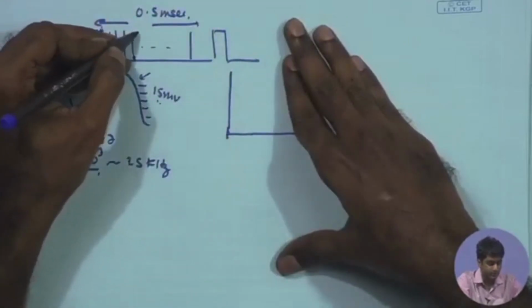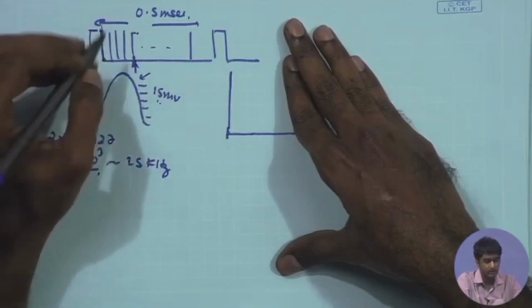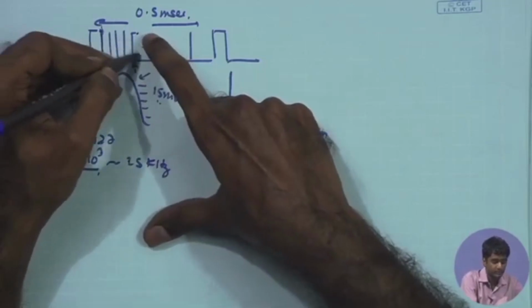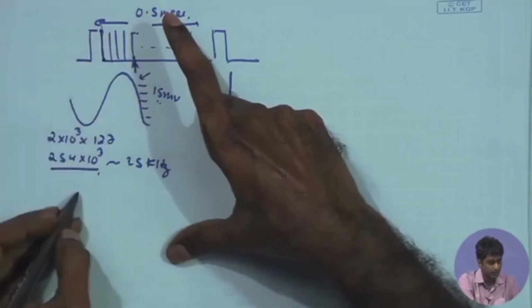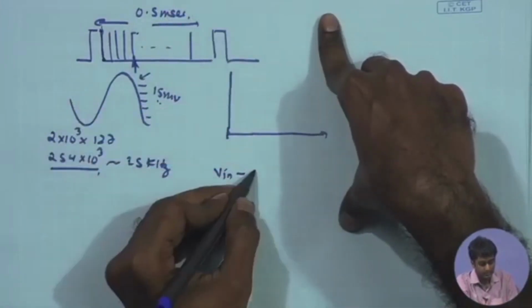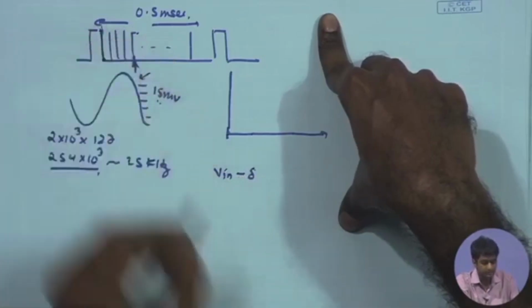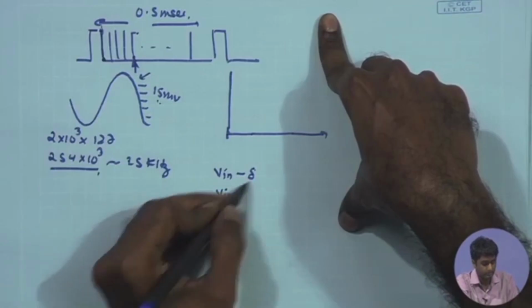So, suppose the comparator is having a transition at this particular positive phase of the clock, and therefore, this would imply that just before this positive edge, the reference signal was equal to Vin minus maybe a small value delta 2, and just after this particular instance, the reference signal has gone up to Vin plus delta 1,